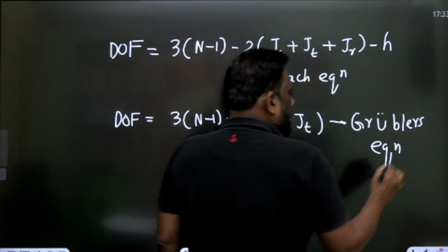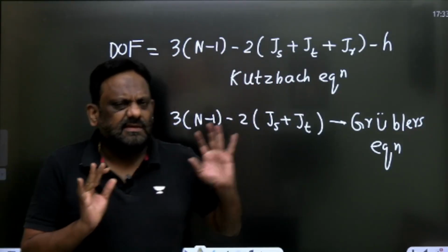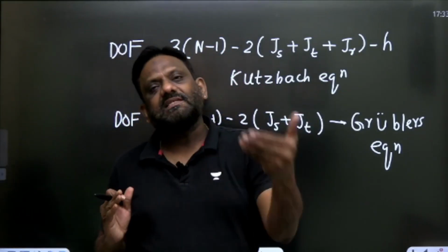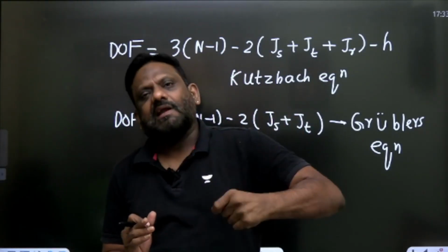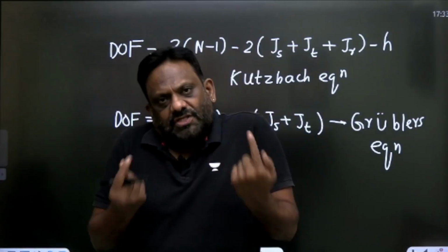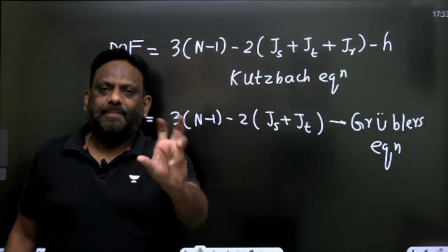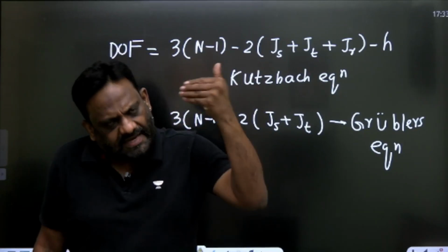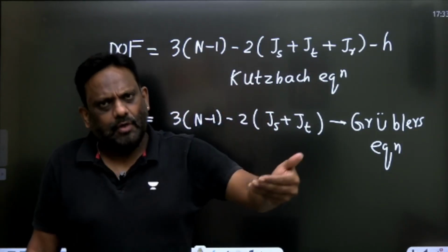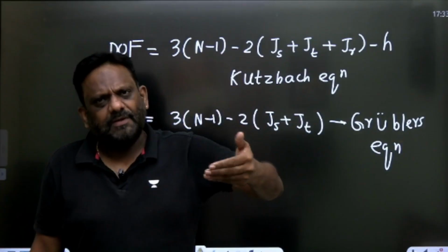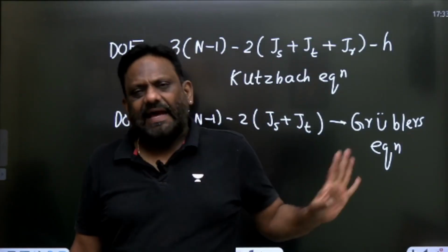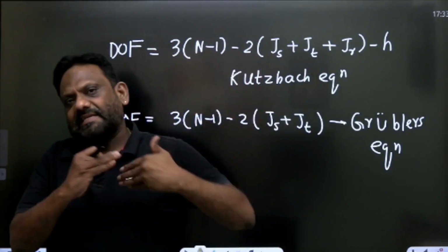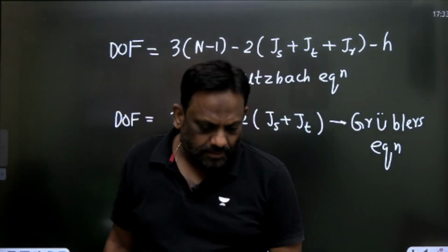Now, my dear students, for the derivation of this equation of degree of freedom, we just take the number of links, how many motions are arrested and how many motions are available, and what type of pairs those are, like binary, then sliding pairs or turning pairs or pure rolling or higher pairs. Higher pairs means roll with slide. Only that. Other than that, we don't take geometry, shape of the link, or size of the link into account. Okay, sirs.